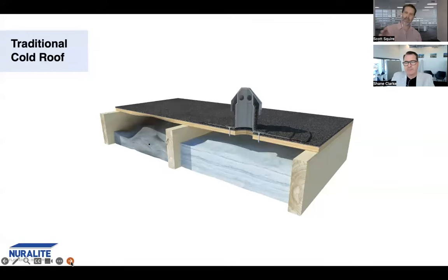So we can see in this render here, you've got lofted insulation fitted between the framing. You can also see that we've got a little proprietary mushroom vent, a thing called a Neuravent there, which is essentially designed to promote cross-flow ventilation of that cold roof. Because, with the new H1 changes, we've got so much more insulation in there, which is great in terms of reducing energy loss through that roof.